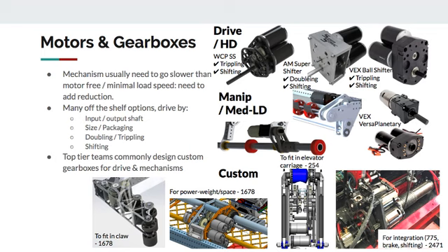No. Oh, yeah, so then there's this other category of like, okay, so you take the smaller motors like the Vex in the bag. They're basically like a third of the size of one of these, so you can't just plug it into the gearbox. The holes don't line up. And there used to be different ways that you would do this, but since the Versaplanetary came out, basically everything revolves around the Versaplanetary. Because it's just such an effective solution to this problem.